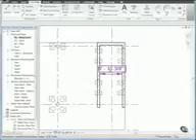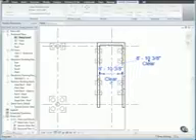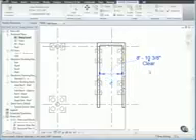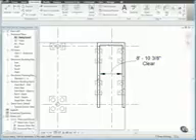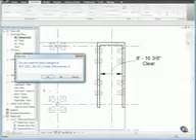Double-click the dimension text. Then in the dimension text dialog, under text fields for below, type clear and click OK. Then select the drag text control and drag the text outside of the stairs. Then press Escape and close the file without saving it, as the next lesson will provide its own training file. And that concludes this lesson.